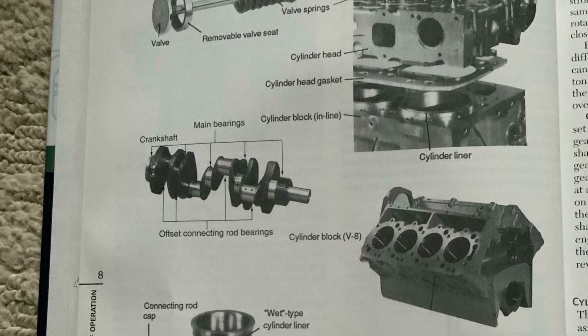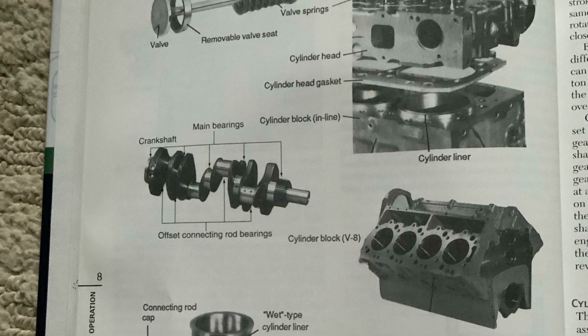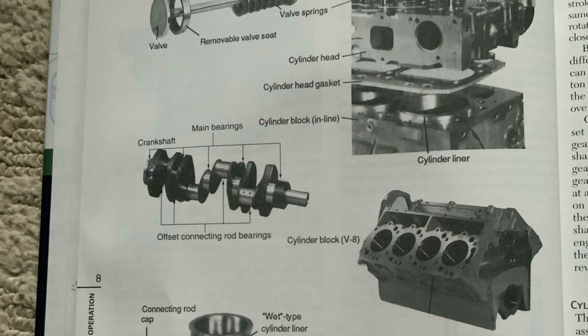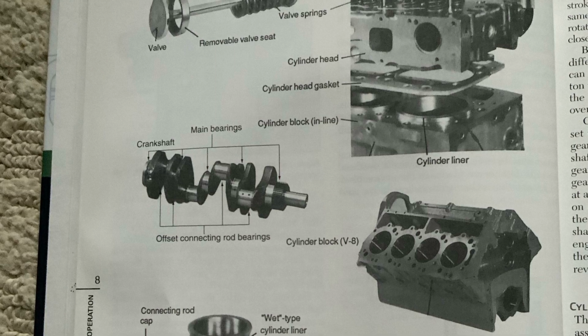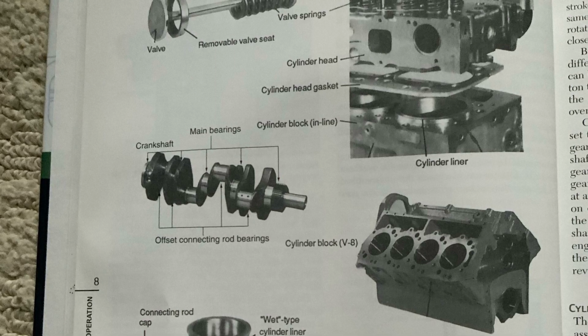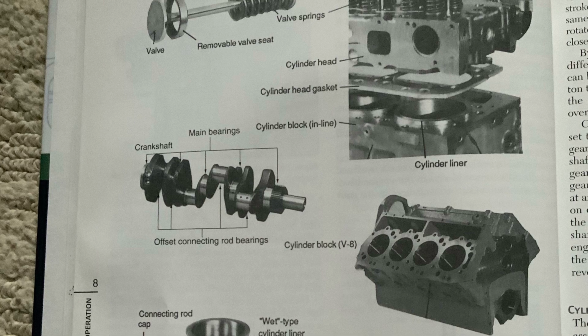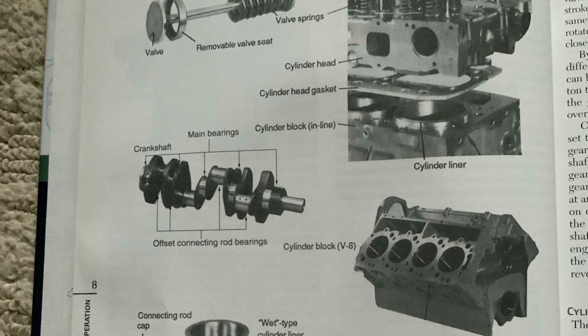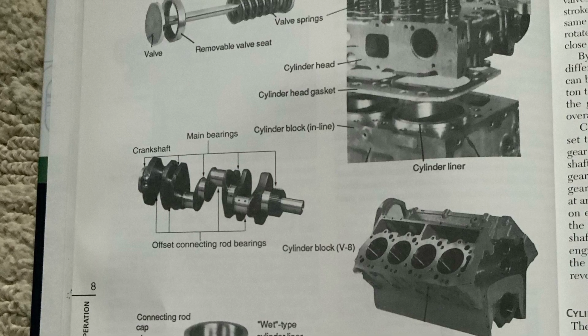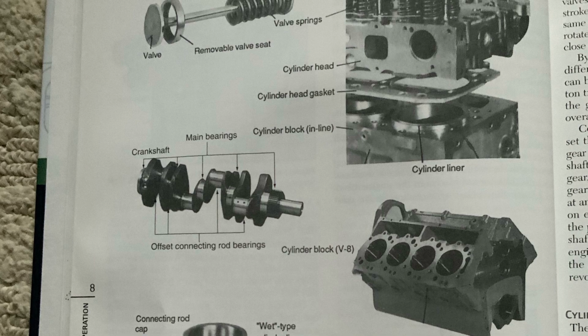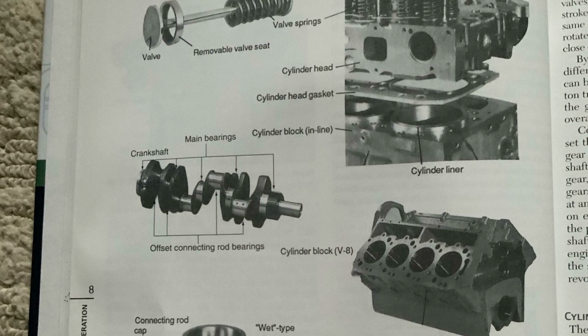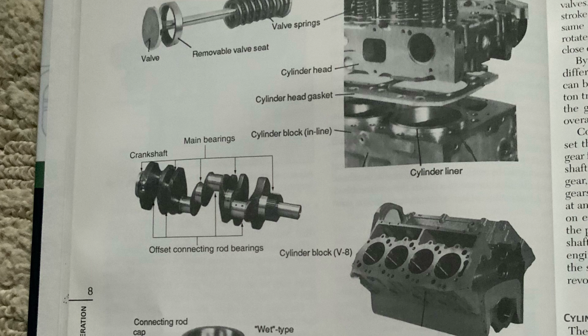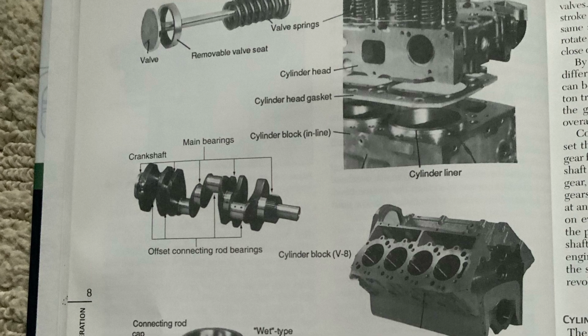A gear key locked to the end of the crankshaft rotates with it. Another gear keyed to the end of the camshaft rotates with it. The valve timing, or valve opening and closing times, is coordinated with the movement of the pistons by linking the two gears with an intermediate gear, a belt, or a chain so that they rotate together.